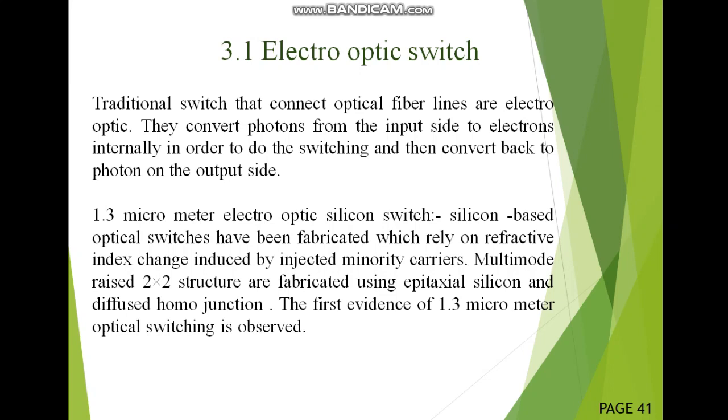For the 1.3 micrometer electro-optic switch, silicon based optical switches have been fabricated which rely on refractive index change induced by injecting minority carriers. Multimode 2x2 structures are fabricated using epitaxial silicon and diffused homojunction. The first evidence of 1.3 micrometer optical switching is observed.